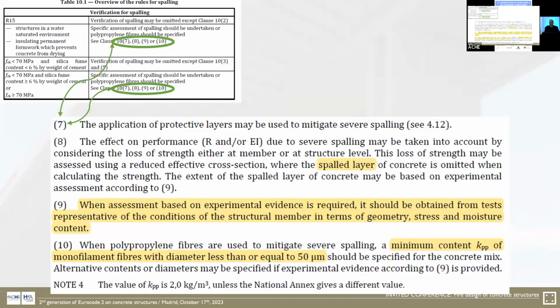It's a complex problem, also because we recently had some evidence of behaviors which are not what you typically expect when you have spalling. I mean, spalling is always like the explosion of concrete chips from the surface, okay? What we had in Milano is specimens, bulky specimens heated up in the furnace, exploding literally, breaking apart the whole furnace, really something which was not expected, and needless to say, with high performance concrete.